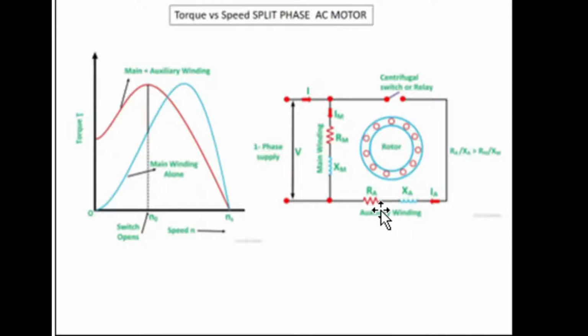When we apply an alternating current to both the coils, the current in the start circuit is going to be higher than that in the run circuit. And by reactance, if you remember, reactance is the resistance that the coils generate when an AC current is applied, and reactance is also measured in ohms.